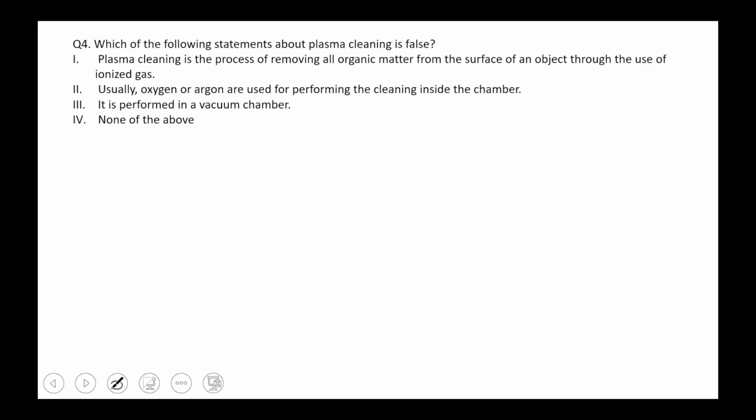You have to take a glass for making any device. If you have to clean the glass, there are processes like RCA1 and RCA2, the reactive chemical process. You put it in acetone or IPA and sonicate for some time. You heat that material, but some organic material will remain on the surface of the glass.